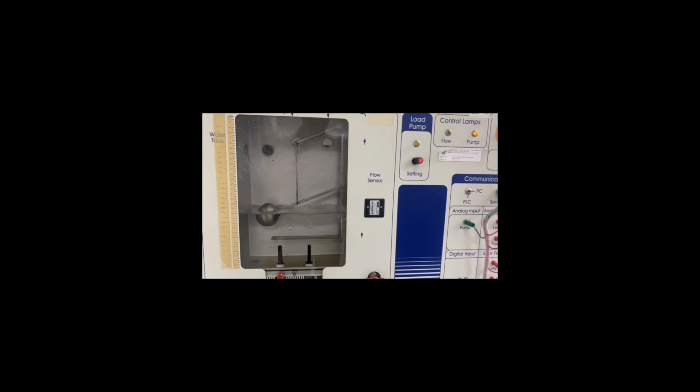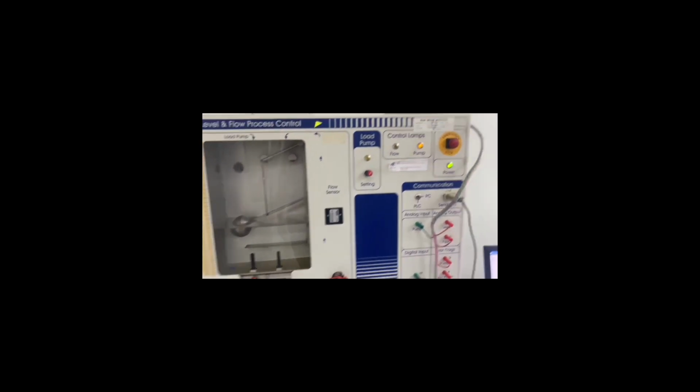For this task, make sure valve A is in open condition, meanwhile valve B is in closed condition, and valve C should remain closed throughout. Record the system output H and the controller output M in the table. For the third task, at the dialog box, remain the set point at 108, but change the KC to 100, and then click run and run the system until it reaches steady state.